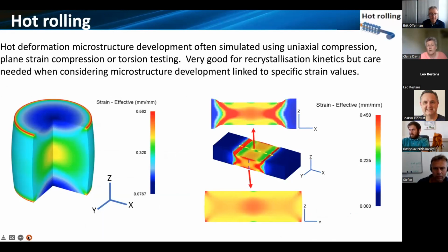Whilst talking about hot rolling, I also ought to mention the importance of our experimental simulation behavior and understanding that, particularly when looking at microstructures, and that's where our focus is today. So for lab behaviors, we can have lab hot rolling. One of the challenges is maintaining the temperature as we go to smaller samples when we do our laboratory hot rolling. And particularly if we're looking for the control for the strain and temperatures and interpass times, it can be challenging in a lab mill.